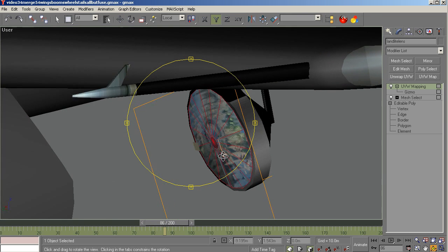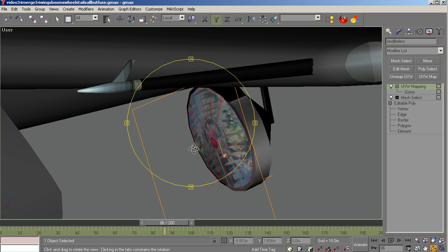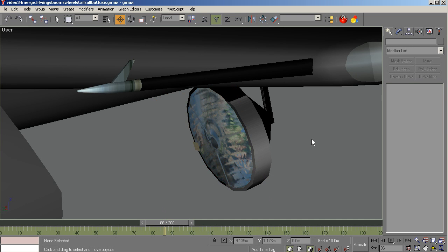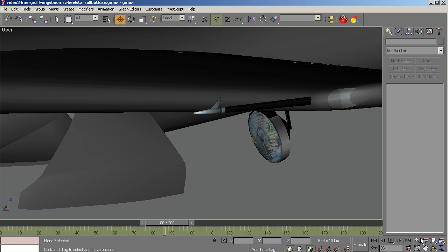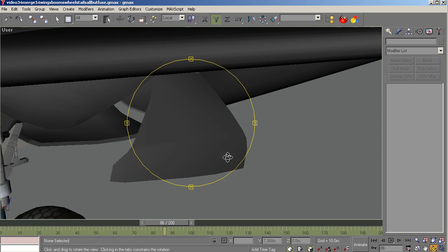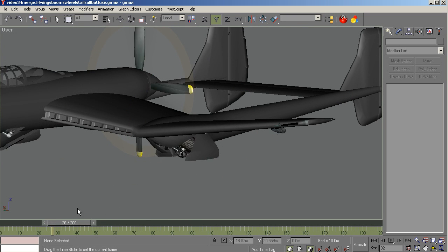So when you set up your parent of the light beam point light here, link it to your lens or whatever is behind it, and then go into local mode and affect pivot only, and set this pivot so that the z-axis is pointing opposite of the beam direction. That's the best I can tell you. I can't explain it, but that's the way it's got to work. So I hope that's helpful.